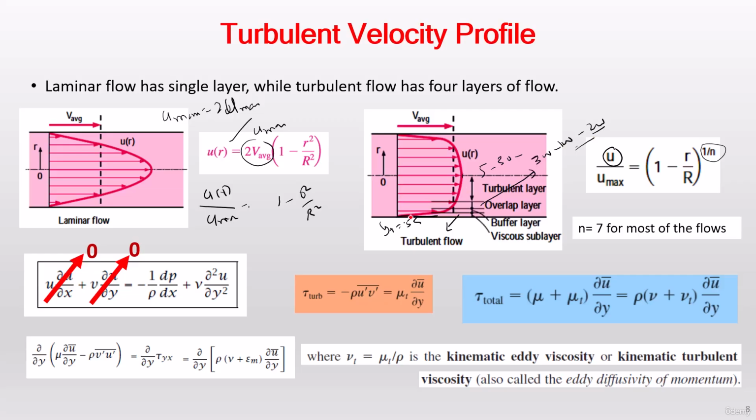So the maximum shear stress is in the wall region, where we are going to have the maximum pressure loss as well. So if you want to predict very accurate values for the pressure drop, the coefficient of friction or the Darcy friction factor, then you should resolve your viscous sublayer. For that we will keep the y plus 1. And also I will give you one more example where I will keep the y plus around 10. I will compare what will happen if the first cell height is not in the viscous sublayer but in the buffer layer. And maybe you can try one more case yourself if you keep the y plus greater than or equal to 30.